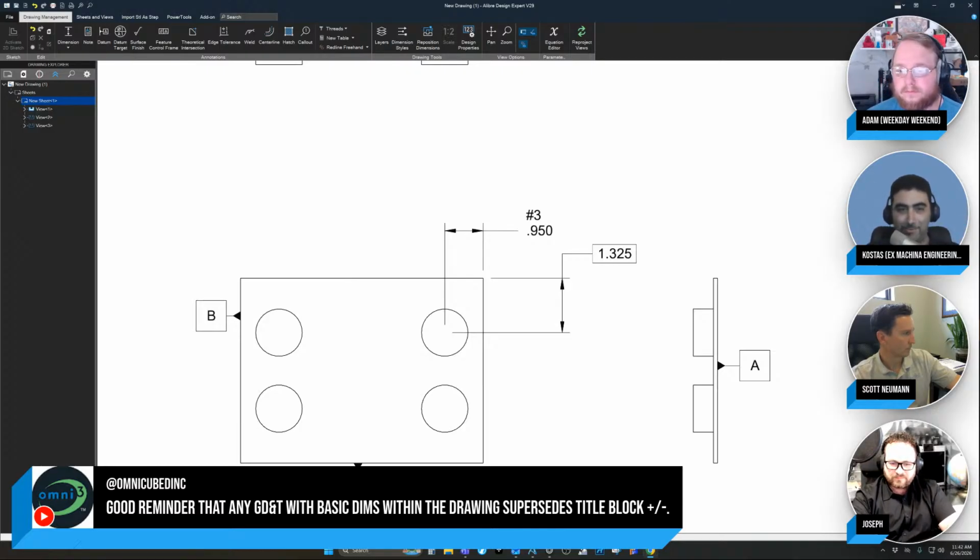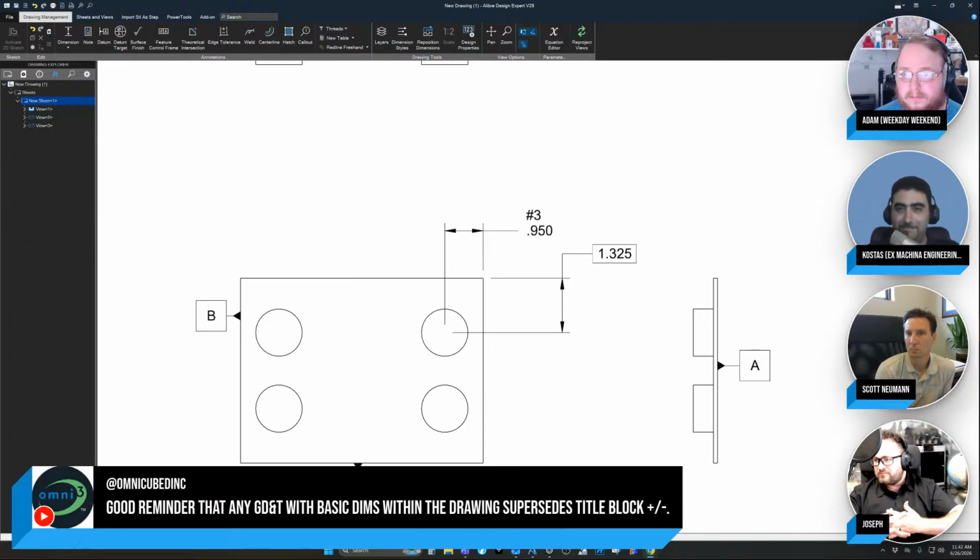And a good reminder: if you are using positional GD&T and tolerancing, it does supersede the plus or minus. Of course, most do actually say unless otherwise specified, but it's always a good reminder. Yep. Fantastic.